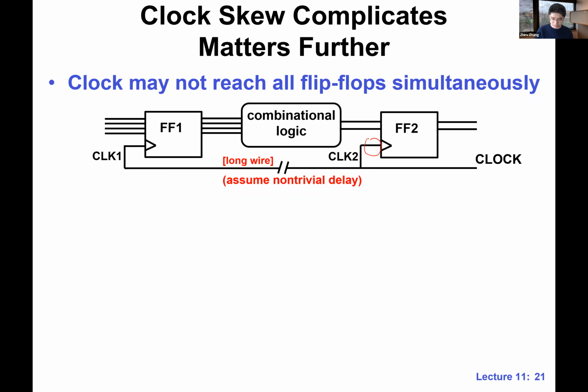By endpoints, I'm talking about these, the endpoints of the clock signal. They can reach different endpoints at the same time. But again, this is just the ideal case. It's actually not practical in the realistic case. So we do have wire delay, even for the clock signal. That's where we may have the skews. So basically, different flip-flops may see the clock edge at different times.